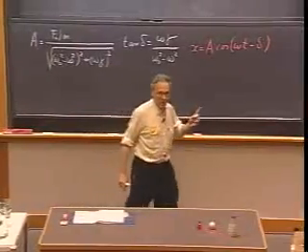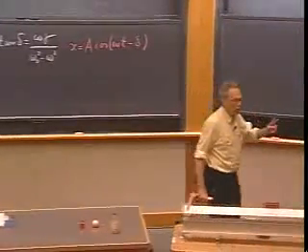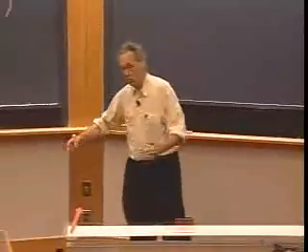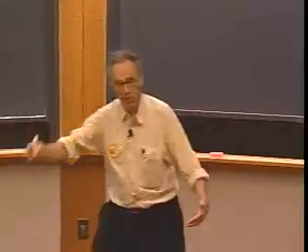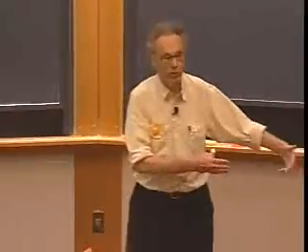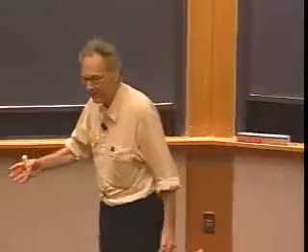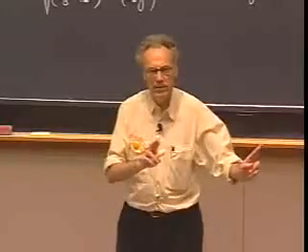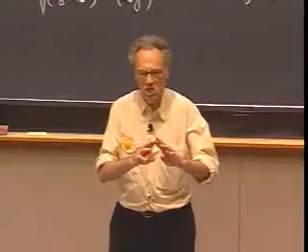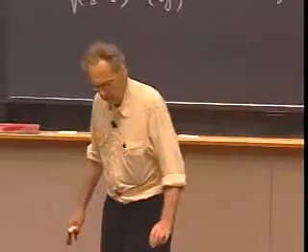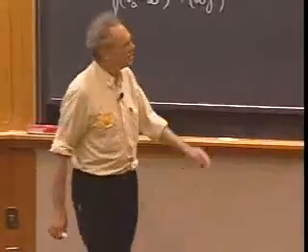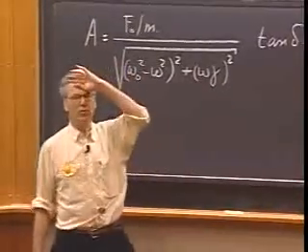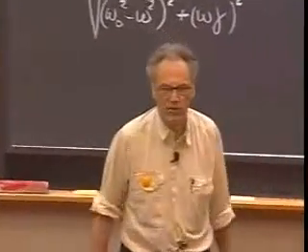Notice that there are no two adjustable constants, which we were so used to in the past. In the past we said, you can start the system at t equals 0, you can define the position, you can give it a certain velocity. So you always expect that in your solution there are two adjustables in order to meet the initial conditions. There are none here, and the reason is that this is a steady state solution, which means the system doesn't remember anymore what the situation was at t equals 0.